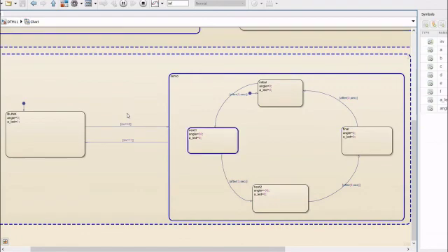When the disks are loaded into the launching unit, during the launching time, the disk which we are launching is launched with any particular angle we desire. So we use the servo motor which is present in the pan tilt servo system, which helps in horizontal and vertical movement of the glass pane or the launch pad. Thereby it is shifted to a particular angle, and the table is being tilted by that angle.